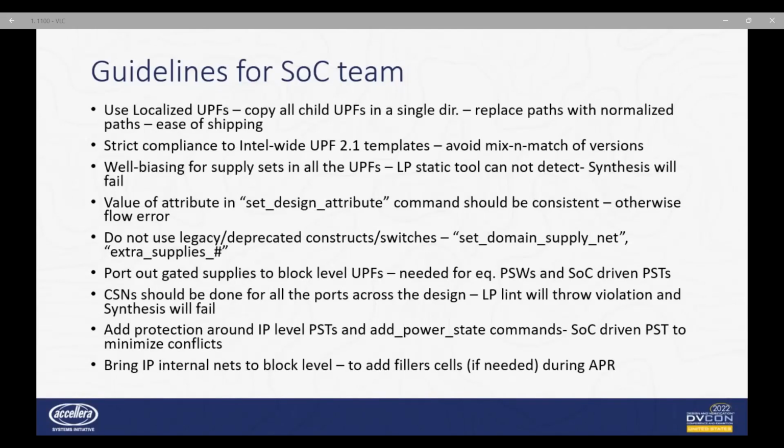The value of attributes used in the set design attribute command should be consistent in all the UPFs. For example, if the value of the attribute is true in the topmost UPF file, the child UPF cannot have a false value for the same attribute.